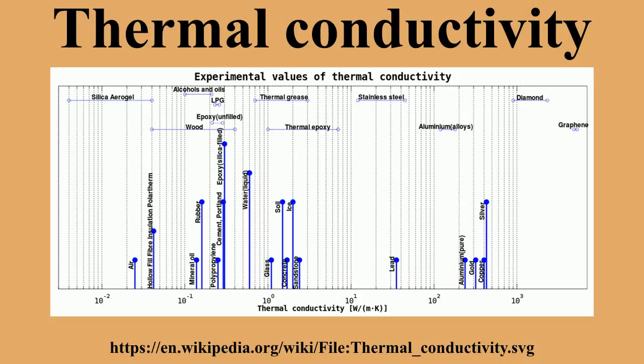Measurement. There are a number of ways to measure thermal conductivity. Each of these is suitable for a limited range of materials, depending on the thermal properties and the medium temperature. There is a distinction between steady-state and transient techniques. In general, steady-state techniques are useful when the temperature of the material does not change with time. This makes the signal analysis straightforward. The disadvantage is that a well-engineered experimental setup is usually needed. The divided bar is the most common device used for consolidated rock solids.